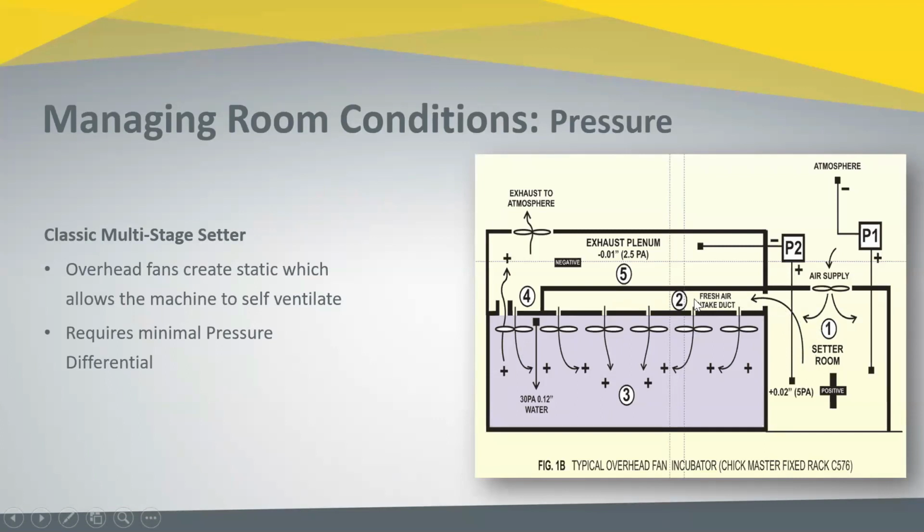This duct internally has openings above each fan. And therefore that opening is strategically located in an extremely negative suction of that fan. And therefore, when the fan is running, that extreme negative just above the fan is what allows that air to be pulled in from that fresh air duct.